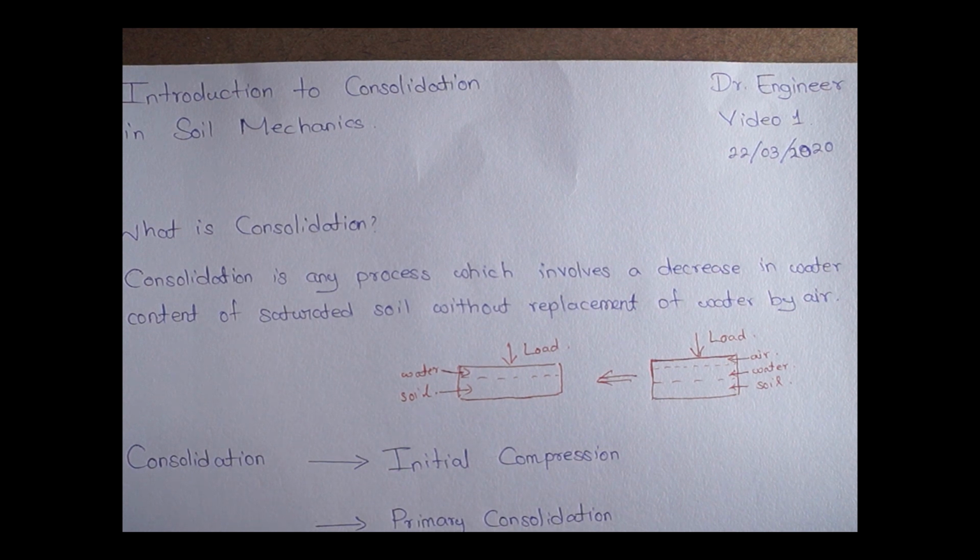So consolidation is a tricky process. It takes long time under static load. There is a replacement of water, and there's another similar process which is compaction, but it is a rapid process. There's dynamic load application and the process is quick.